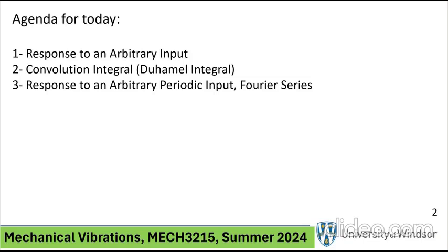Now, it is worth reflecting back and seeing what we did in the past 7 weeks. So the first 3 weeks of the course dealt with free vibration. In other words, there was no forcing function involved. We had the mother of all equations, namely m x double dot plus c x dot plus k x equal to 0. Now, the fact that it's equal to 0 means that there are no external forces applied to the mass. And of course, there are initial conditions involved. For example, given initial position and initial velocity, we can go ahead and solve that, and we did it in its entirety during the first 3 weeks.